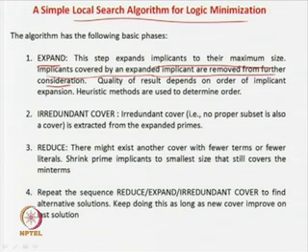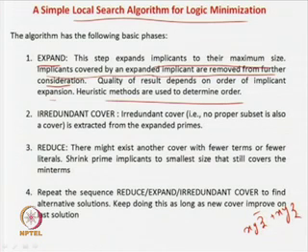Quality of results depends on the order of implicant expansion. Heuristic methods determine the order. So this step expands implicants to their maximum size. Say, for example, you have xy, and it is a function of z. You can expand it to xyz' plus xyz. So you try to expand, but you do not expand wholly. You take one literal at a time, like x, y, z, whichever one, and you expand the function as much as possible. But in canonical representation, you have to expand all the terms in all possible literals.